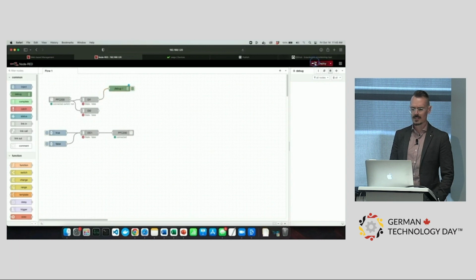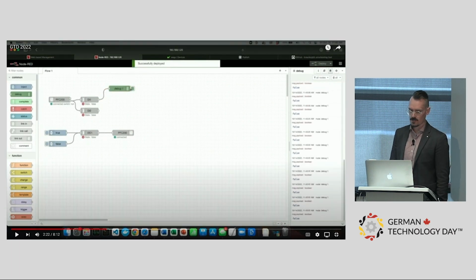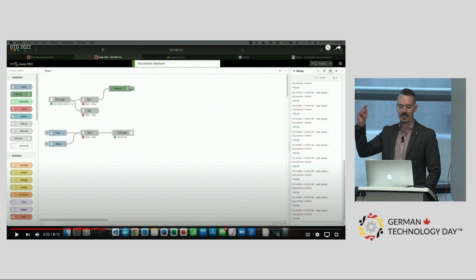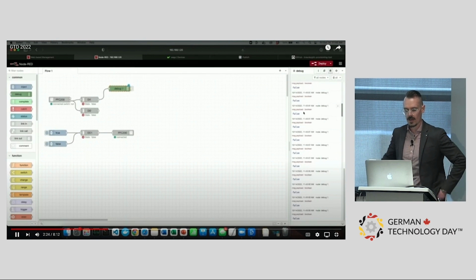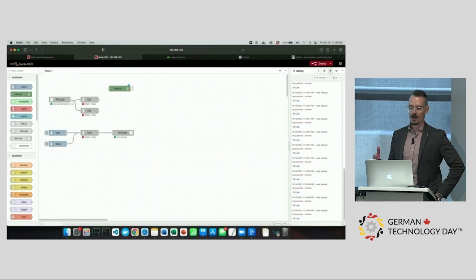And then I'm connecting what's called a debug node. And the cool thing about the debug node is, you see I just plugged it in and turned it on. What that allows me to see is the value that's supposed to be coming out of the node. Because the information in Node-RED runs from left to right, I'm basically just mapping and seeing the value that's popping out of this node. So on the right here, you can see it's coming out at a cyclical value because of the way that the K-bus container is running. But it's pulling this data out, and it's showing me, hey, I'm getting a false value when I submit false to it.